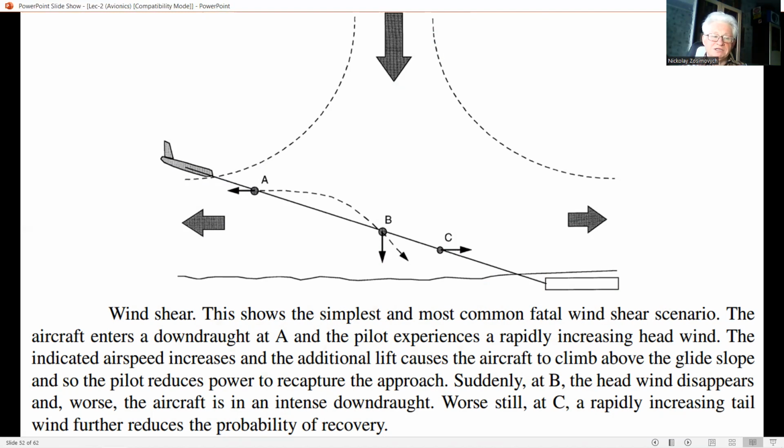Traffic collision avoidance systems, TCAS, provide traffic conflict escape guidance and are of great benefit in preventing mid-air collisions. Guidance, however, is provided head down, so the pilot is maneuvering on instruments while trying to acquire conflicting traffic visually. The HUD enables the escape maneuver and search for traffic to be accomplished head up.